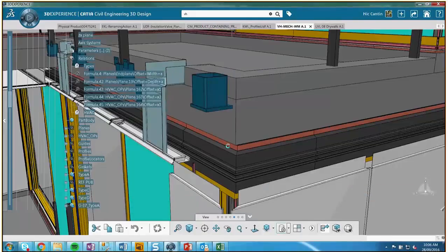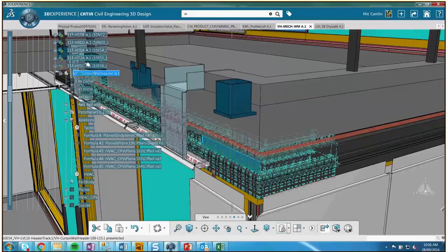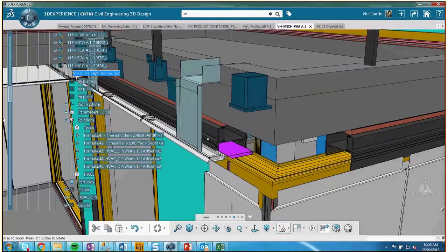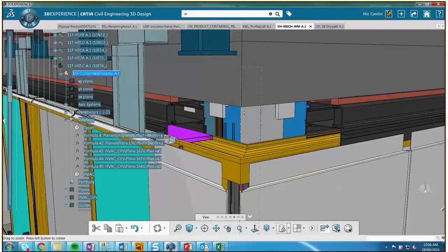Any other questions? Another thing for the whole BIM world and VDC is that coordinating a design model is a good first step, but you don't have all the information. You don't have shop drawings. You don't have the actual size of ducts, which can change post 100% CDs. To be clear, every embed plan is coming from this model.